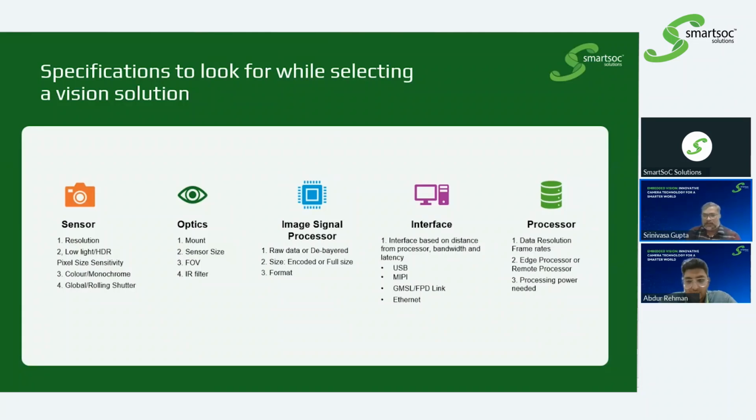Okay, so this image signal processor will do the entire debayering function, and also noise removal and image segmentation, and whatever processing we need to do, like color sharpening, gamma correction, and contrast value changes. These are all very important factors. So in industry, this is what you call camera tuning or image quality tuning, where we set all our required parameters.